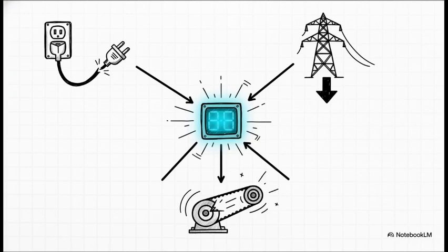To test a USF, or supply mains undervoltage, you can drop the incoming voltage threshold on a testing bench. And to trigger an OCF, an overcurrent fault, you can artificially drop the motor's current limit parameter down below its normal operating draw. By forcing these faults intentionally, you get to safely watch exactly how that 4-digit display reacts, so you aren't surprised when it happens for real.